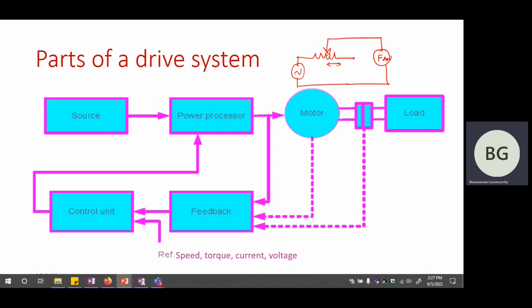Whereas if I am going to apply the entire amount of voltage to the fan, which means I'm going to just connect it here rather than here, then the entire voltage is connected to the fan, in which case the fan will run at full speed. So the regulator available in your home essentially does the job of this resistance. Either it drops part of the voltage or the entire voltage is applied to the fan. So either way is possible.